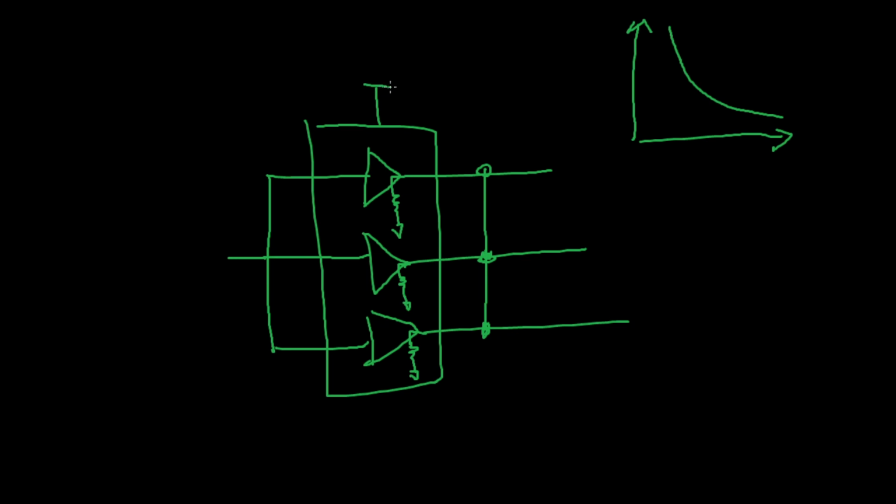So if you have a device that's designed, for example, for a 5-volt supply, but you're running it at 2 volts, then you're going to be operating somewhere at the higher resistance end of these MOSFETs. And what you can do to reduce that is you can put 3 in parallel and you'll end up with 1/3 of the resistance instead of this resistance up here.